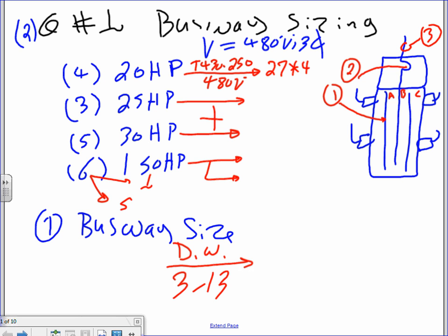Very easy. Then the second one, guys, will be 34 amps times 3. The fourth one would be 40 amps. These are all amps times 5. Now the last one, I split it into 2. Anybody know, guys, why I split the last 150 into 2? Yes, the largest one plus all the others. That big boy is the largest motor, so you need to increase one of them 25%.